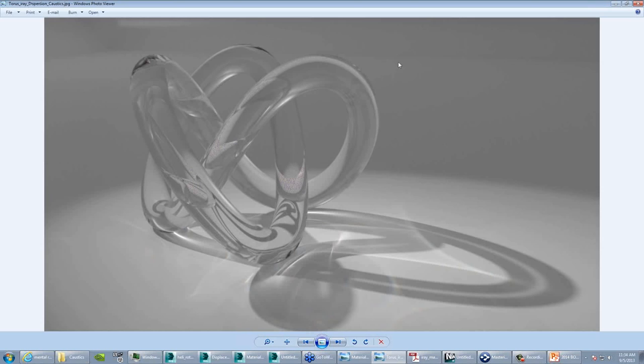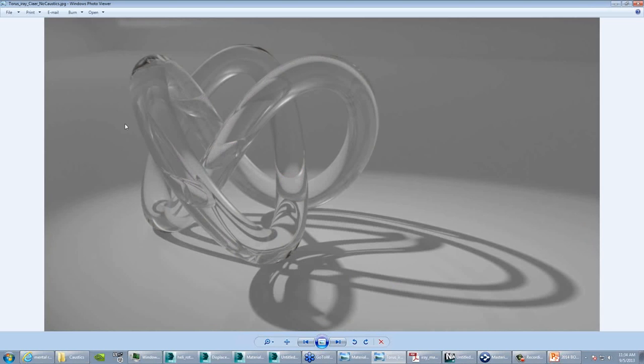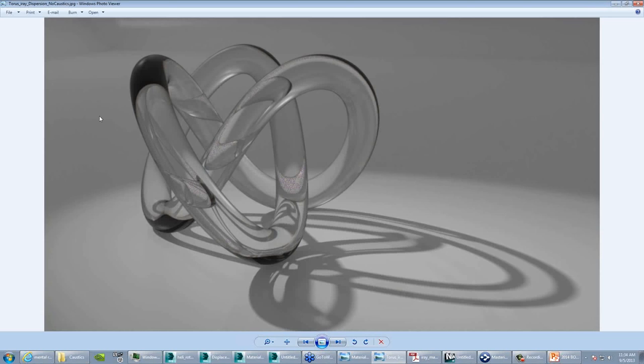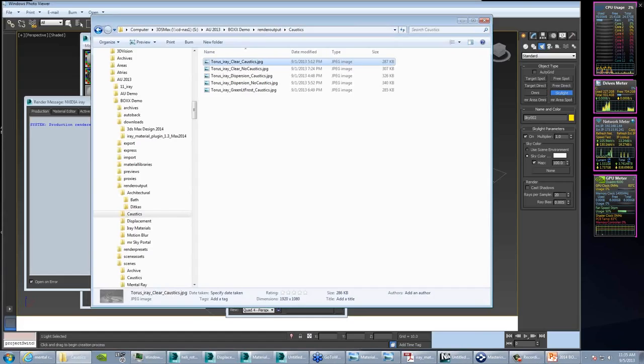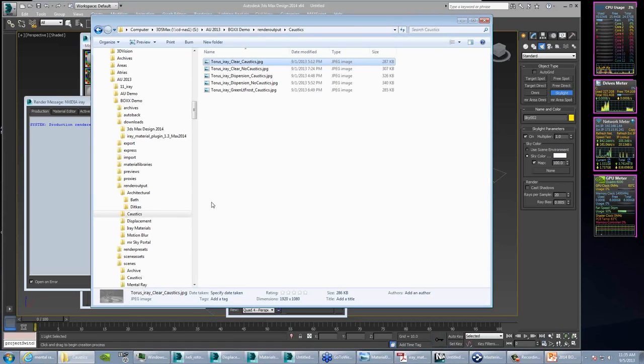The Iray layered material, the new Iray material, supports dispersion, and with curved materials, it's not a real great option, but it can affect some of the transparent materials in there. But as far as caustics are concerned, it does a brilliant job. It doesn't add a huge amount to the render time compared to adding caustics inside Mental Ray, but it does have a bit of a price to it time-wise. So do a trial, make sure that it's needed for that particular scene, and enable it if you need it. So it looks great.